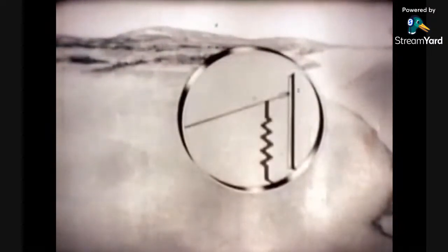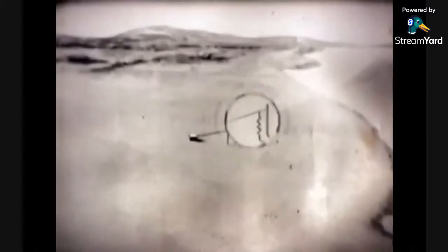Such an antenna can be made unidirectional by adding a resistor at the end of the wire, which thus reduces the wave lobes opposite to it. The resistor is grounded. In this antenna, the resistor dissipates the energy which would create lobes opposite to it. Thus, the effective radiation is in the direction of the resistor.